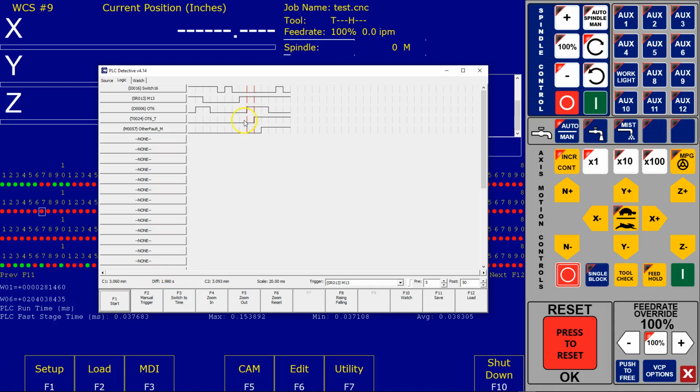So this output turned on, and then within 2 seconds that timer got set, and of course once that timer got set, we see that this other fault ended up being set. If you wanted to, we can even take a look from that point to that point. That's only 20 milliseconds, so that's one complete pass of the PLC program.